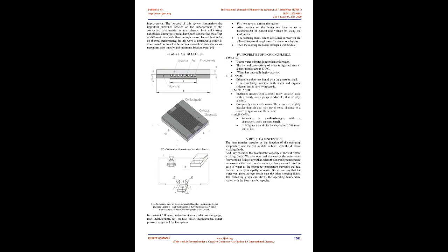2. Mushtaq Hassan et al. state that in this paper, the use of phase change materials, PCMs, in a microchannel heatsink, MCHS, is numerically investigated. Air is first used in the heatsink, and then four phase change materials, paraffin wax, eicosane, P116 and RT41, have been used as cooling mediums in different types and configurations at different ambient temperatures. Constant heat flux is applied on the base of the heatsink, and mixed convection and radiation boundary conditions are applied at the top surfaces of the heatsink.